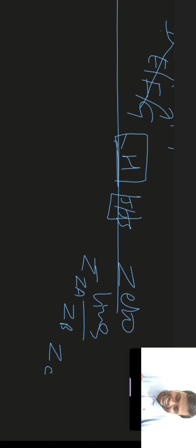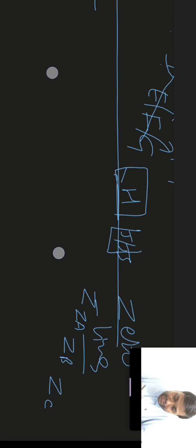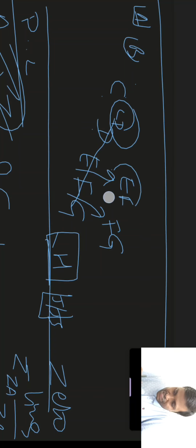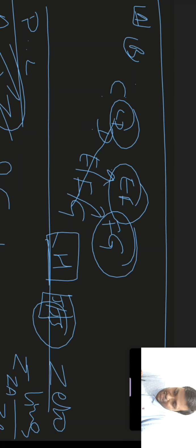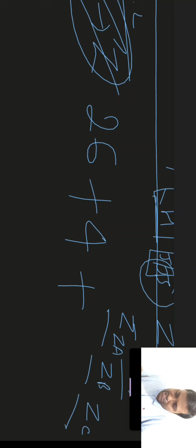So how many total fundamental deviations are there? Let's count it. A to Z in the English alphabet there are 26 letters. So 26 is this one. After that there are CD, EF, FG and JS. So these 4 fundamental deviations are added. After that there are 3 more fundamental deviations, ZA, ZB and ZC, and these are 3. So altogether these are 33.